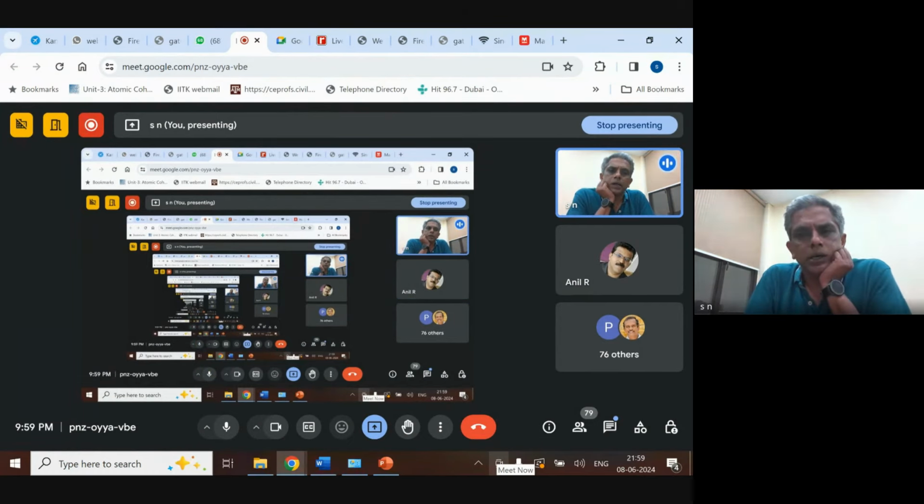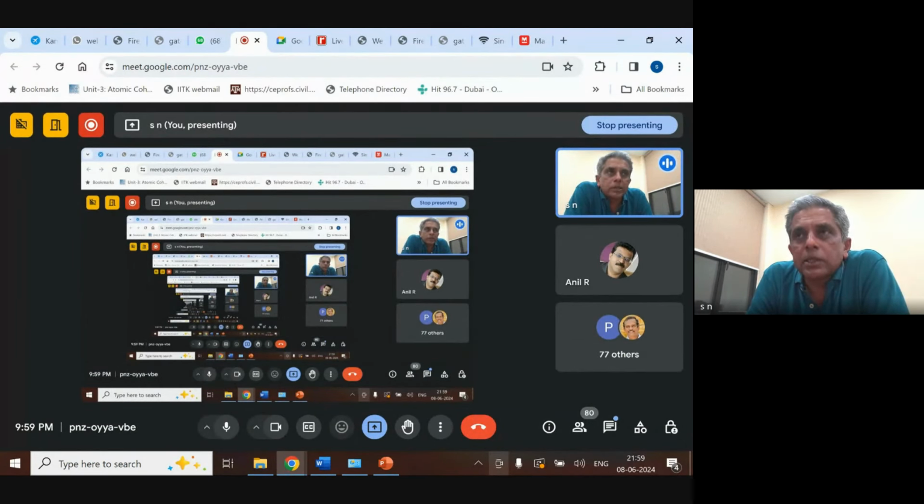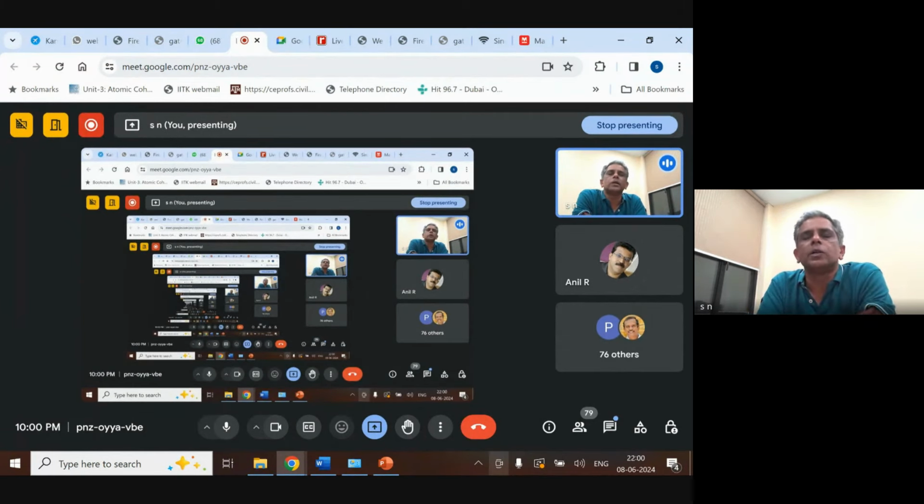Well, it is not only strength that is part of the evaluation. One is strength, and the other is durability, which is very significant in ensuring long-term performance of this material. The durability test, like I have mentioned, is a 12-cycle test, and every cycle, if I remember correctly, takes somewhere around 40 to 60 hours. I think somewhere around 2 days is what every cycle is, which means 12 cycles is 24 days, plus 28 days of curing time. The test is conducted on a 28-day cured sample.